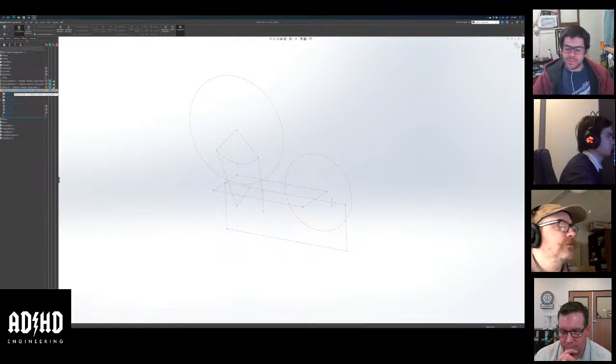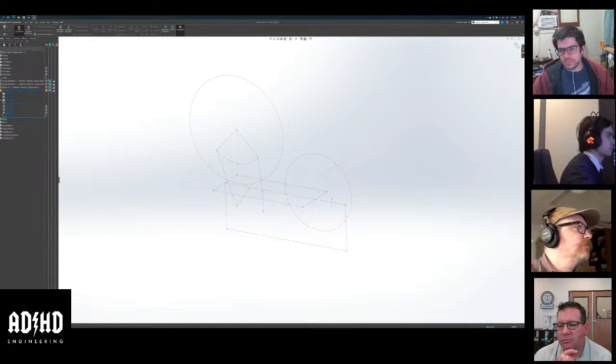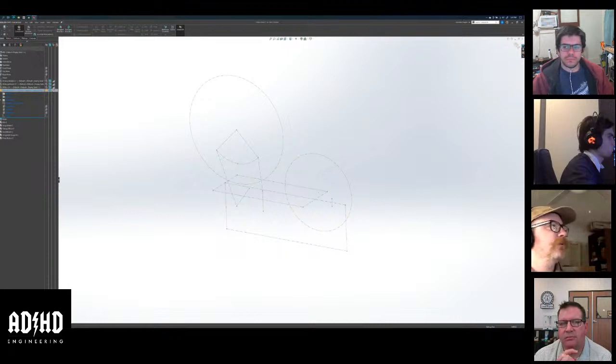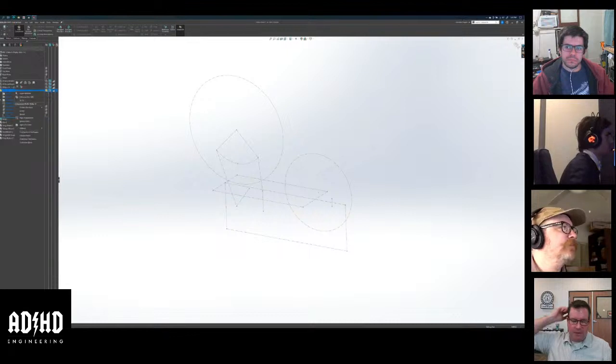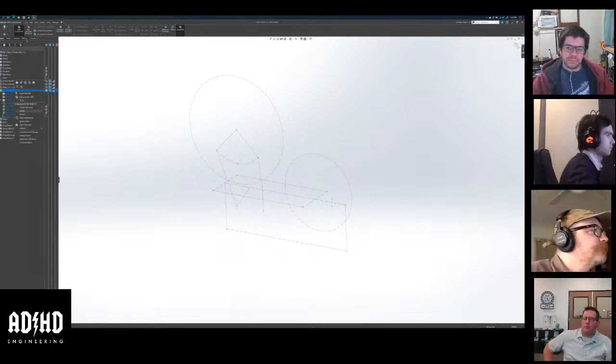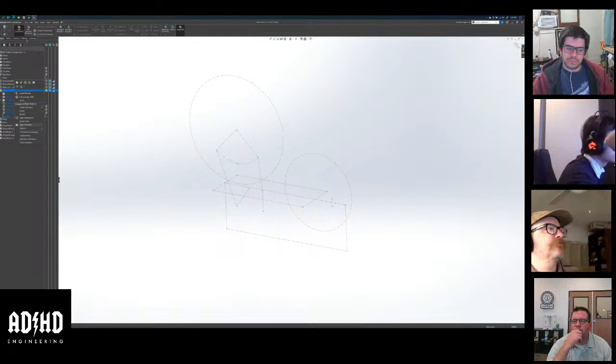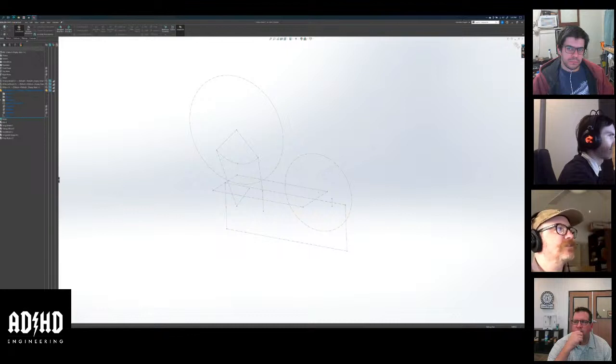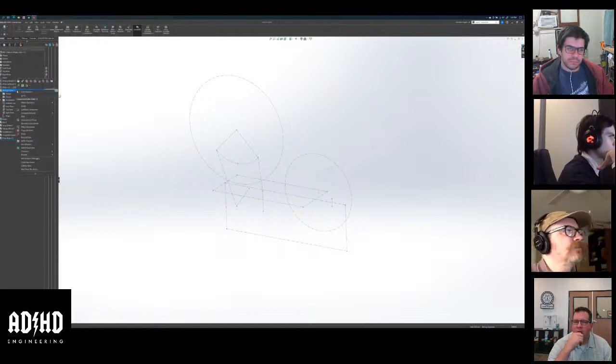Right. Yeah. Okay. So typically I would do that here. I'm editing the part, so I can't really edit the equations here. So polar roller number 1, we are editing that now. Remember, I have fixed this. There's an F here, right? But once I close this, I can make it float. In fact, let's do that now. Edit component, we'll make it float. So it shows up here.